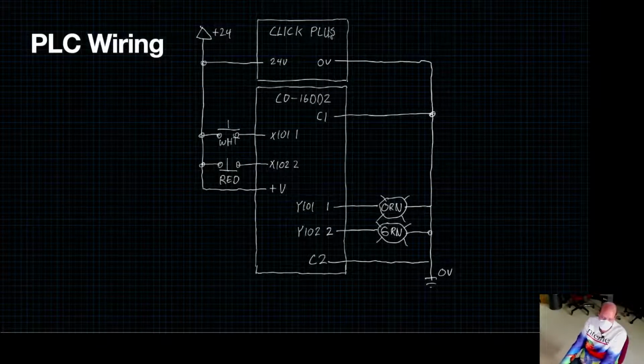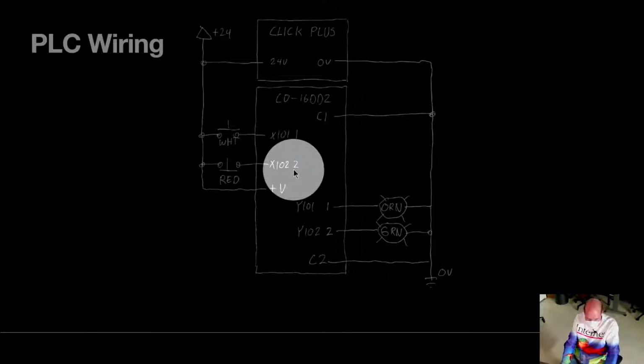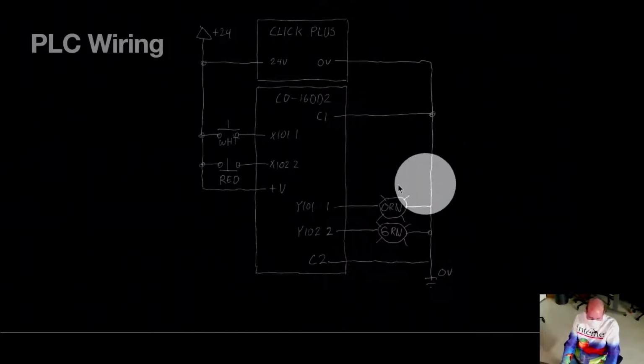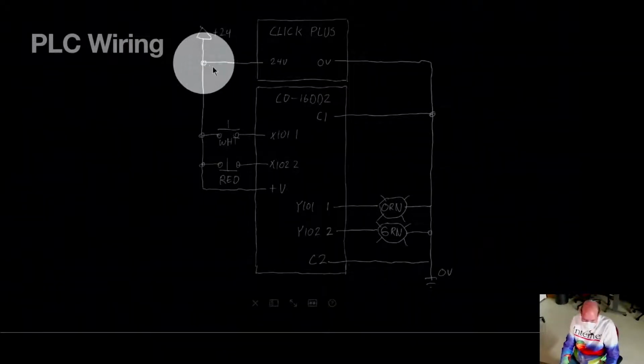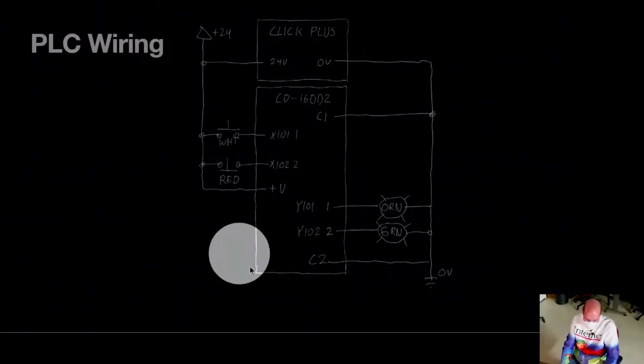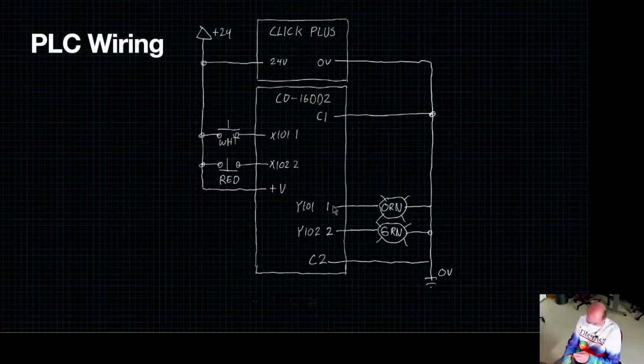Awesome. So yeah, this is a tremendously simple example of a simple PLC with two inputs. Again, we have a normally open push button and a normally closed push button that feed into inputs on the PLC. And then we have two lamps. One's orange and one is green. I'm sorry if you're colorblind, that's what I bought. And then the PLC is powered by 24 volts and 0 volts, and then there's a couple other connections that make the inputs in the PLC work.